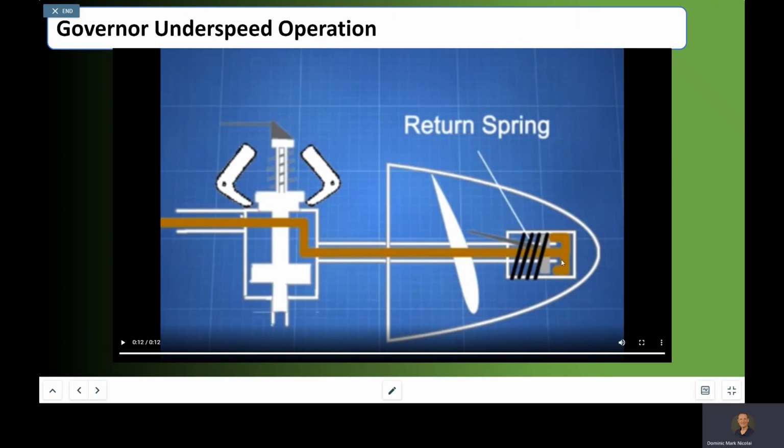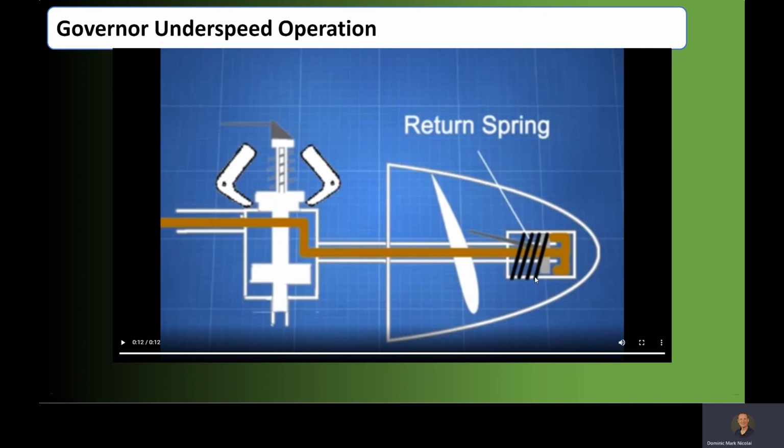So what's up inside here? There are a couple different things happening, four to be specific. First of all, you have a spring in there that helps move that blade angle. That's one of your forces. The second force is going to be counterweights. They'll be placed so that we naturally go to the low blade angle position.